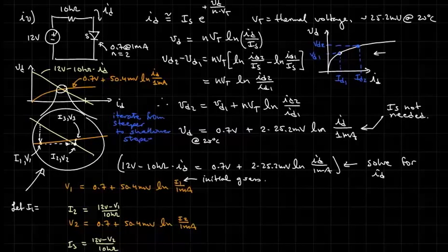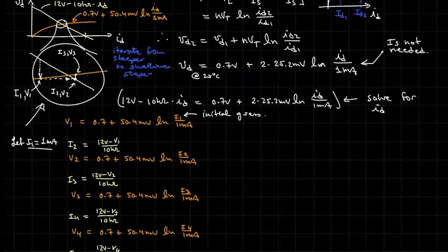And we want to make sure that that initial guess is a current that is less than what we anticipate the current being, so that we're to the left of the intersection. We can make a rough estimate of the current by assuming that the diode has a voltage of, say, 0.7 volts, which you've done previously, and that gave us a current of 1.13 milliamps. So if I choose 1 milliamp, I think I'm going to be to the left of the solution.